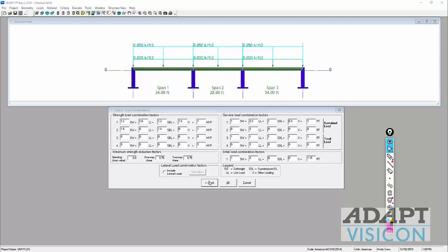Finally, we can determine the different load combinations at strength level and also service level. So in this case, we're designing these as gravity-only members for these beams. We have a couple of strength combinations, including dead load, live load, self-weight, and also the hyperstatic or the secondary actions from the post-tensioning, and also service combinations that we'll use to evaluate the stress and deflections.